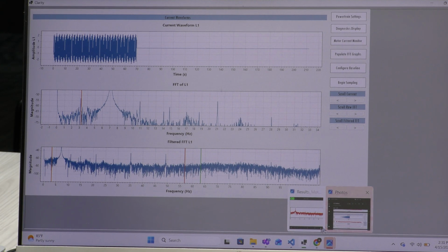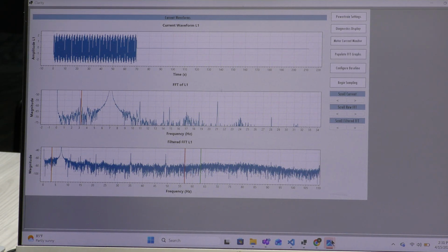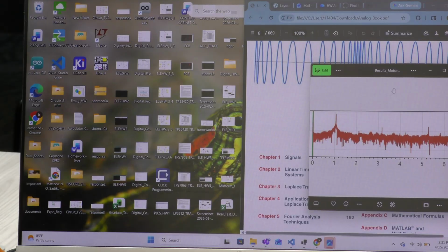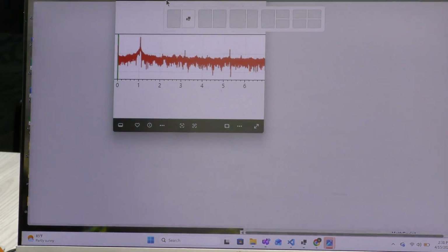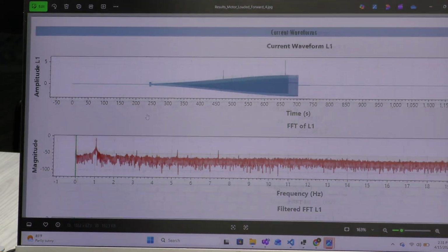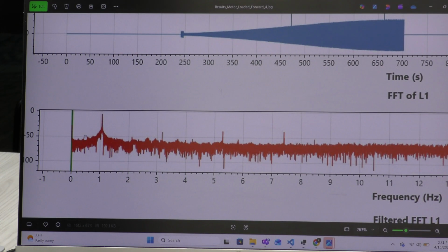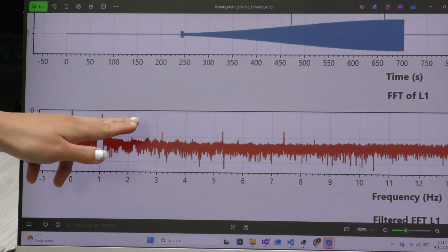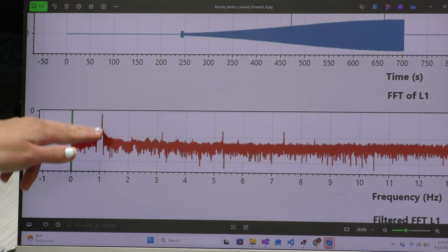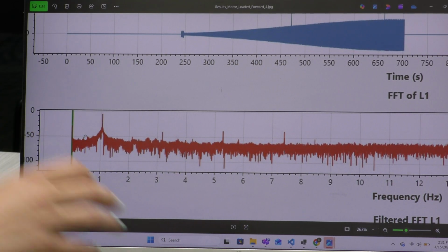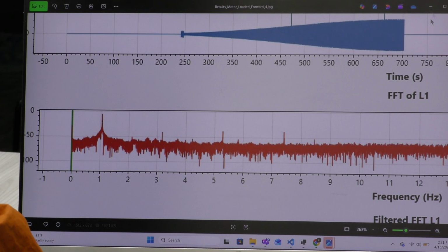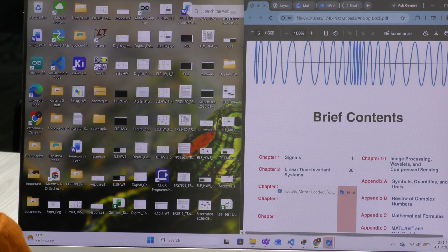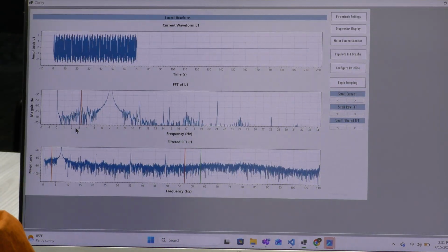And you basically have a baseline current, or some baseline data that you'd compare it to. This is what the motor gearbox looks like typically. And you can see that there are no spikes here at all along this peak. But in the damage data, there is a spike.